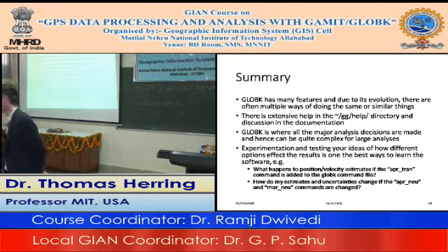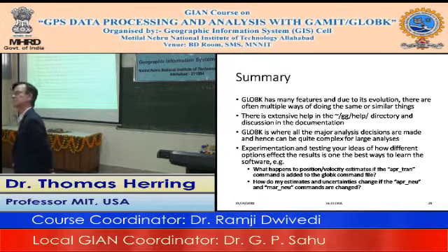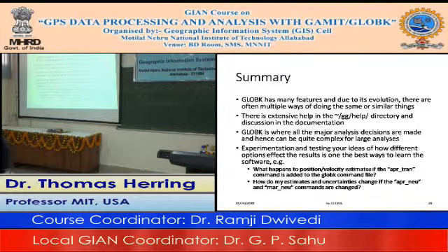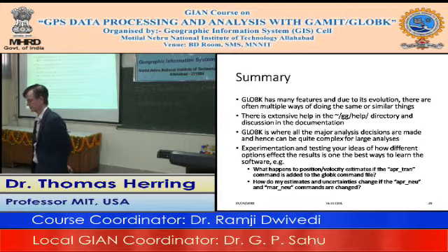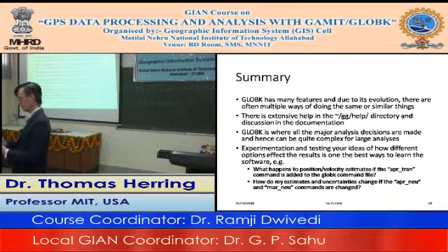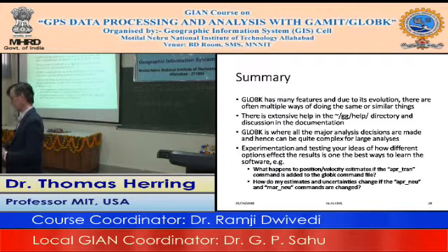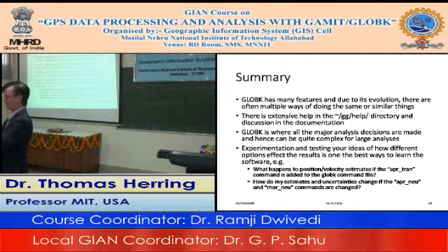In the example you showed, there is a prior noise and there is a process noise. The process noise means the computational process noise introduced by the Kalman filter, because of numerical errors like that? Yeah, so in a Kalman filter, the evolution of the model is that you have a certain uncertainty now. With the process noise, that position will change randomly, and the process noise is the variance of that change. That just gets incremented forward. You hope your next block of data has enough uncertainty that it undoes that change.